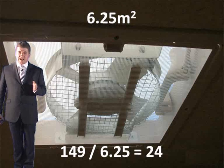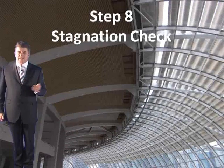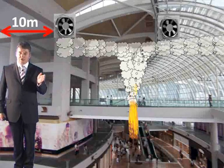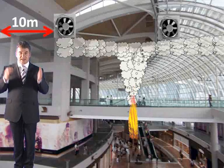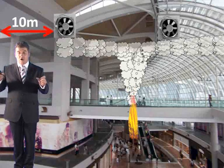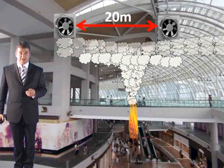Well, before you decide this, you've got to carry out step 8, which is the stagnation check. And what this is saying is ventilators, for natural, should not be more than 10 metres away from an edge, and they shouldn't be more than 20 metres apart. So these are the key rules. You can't put a ventilator more than 10 metres from the edge of a reservoir, or have more than 20 metres in between the actual ventilators.